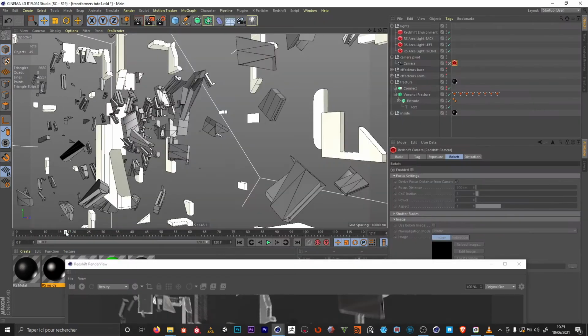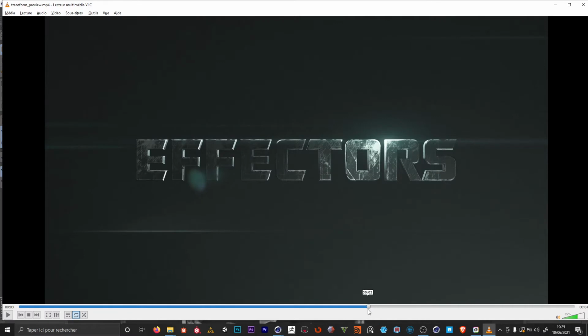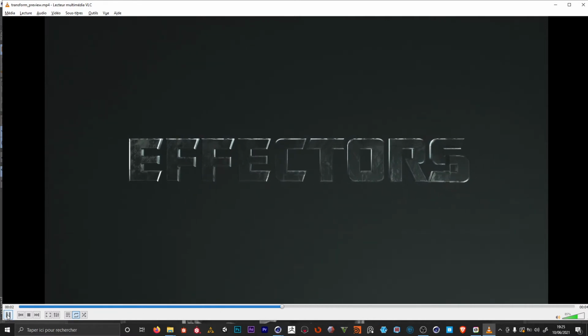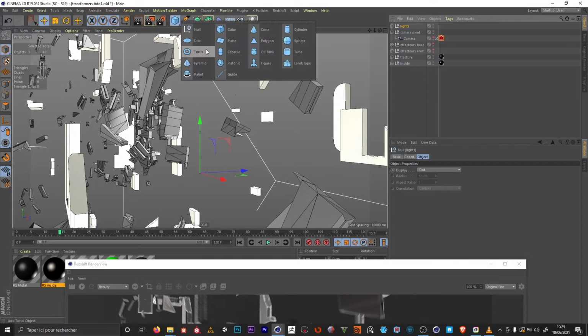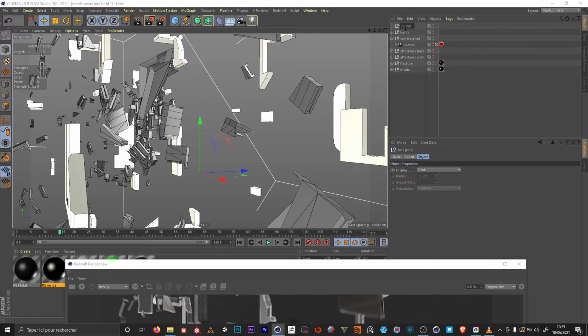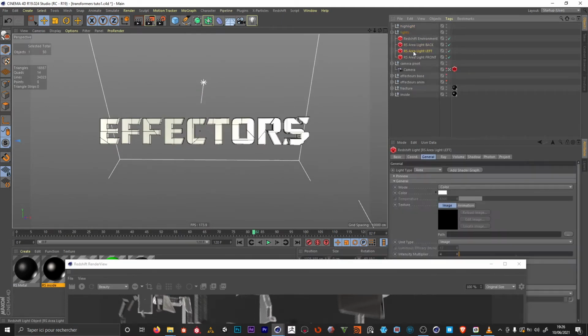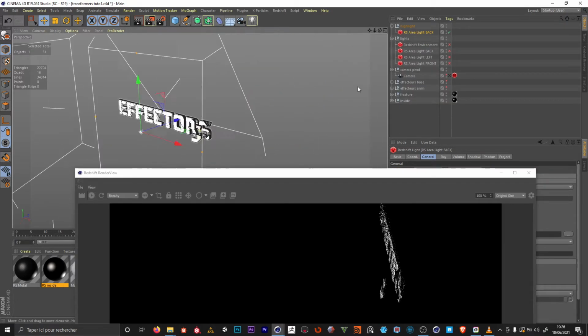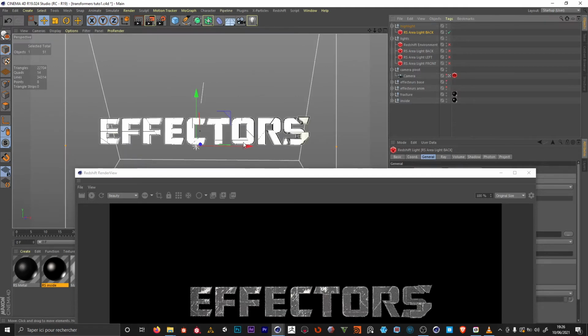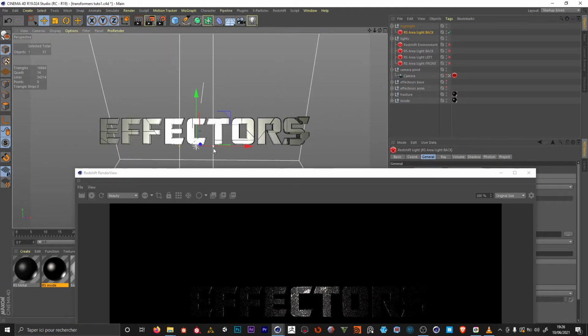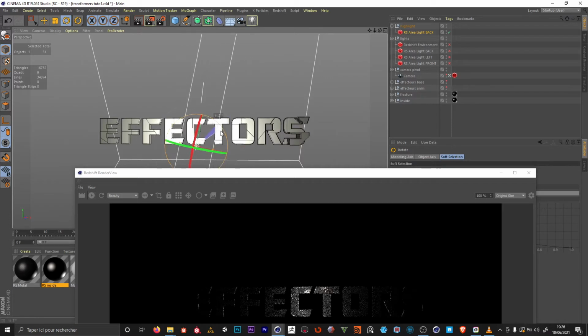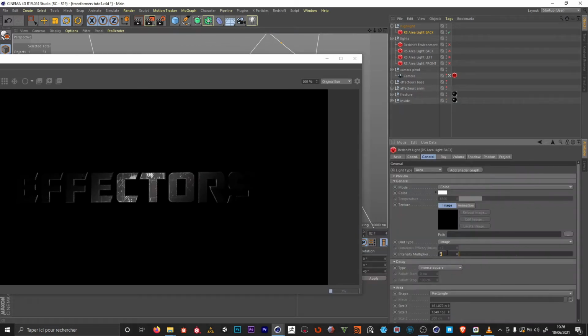And finally, the last thing we want to do is this light sweep on the reflections. So we're going to add a new null, which will be the highlight. So for the highlight, we're going to just copy one of our array lights. So I'm going to deactivate everything else. I'm going to place this one in front of the text. I want this to be really thin. And I'm going to rotate it a little bit. I'm going to increase its intensity, maybe 10.